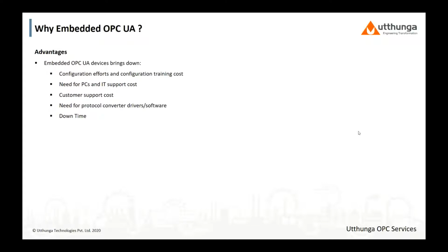A few more advantages. Having embedded OPC in devices brings down configuration efforts, configuration training costs, and the need for several PCs, because usually PCs with OPC servers installed are used in between to gather data from the down layer and even from the PLCs. Also, when you have a PC on the factory floor or in the processing plant, those PCs again require additional IT support.